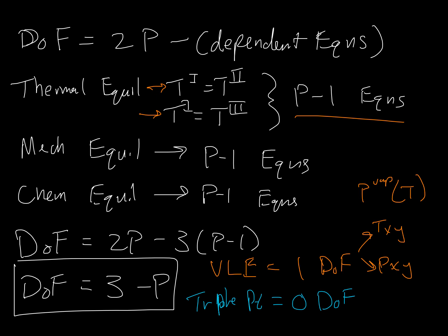They're kind of neat. Okay, so the Gibbs phase rule defines the minimum amount of information that we need in order to say what the state of the system is in terms of the phases. But it doesn't tell us everything we need to know about the properties because we don't know how much material is in each phase. So in addition to the Gibbs phase rule, we also need to have access to a material balance to some extent. What is the fraction of the material in each of the phases? And then from there, we can piece together what is the total enthalpy of the system and what is the total entropy of the system. Right? It's a 50-50 mixture. That means the liquid is bringing half of the enthalpy and the vapor is bringing half of the enthalpy. Does that make sense? So it doesn't tell us absolutely everything we need, but it defines the states for the phases of the matter.